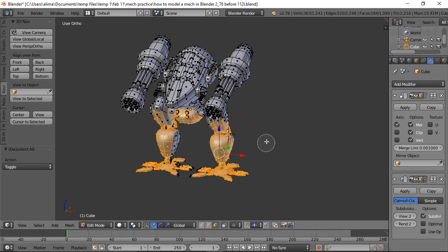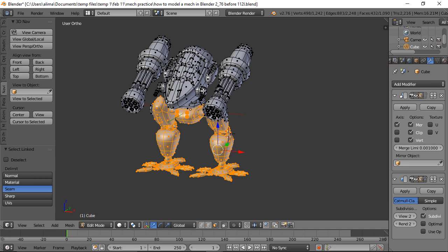So we have that geometry there, so I'm going to right click to get out of paint select. I'm then going to press and hold Control, then press L to select the geometry that we just had a piece of. I'm going to hover here, then press L, hover here, press L, and repeat on each piece. Again, these are the different pieces that I want to be hard. I'm going to hover here and press L as well.